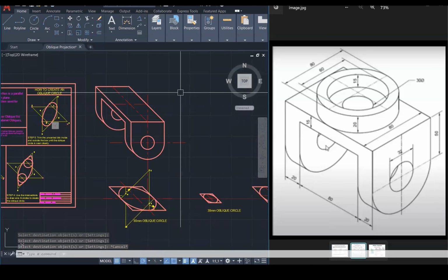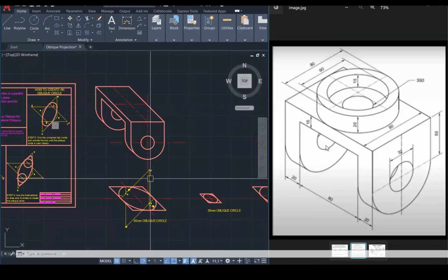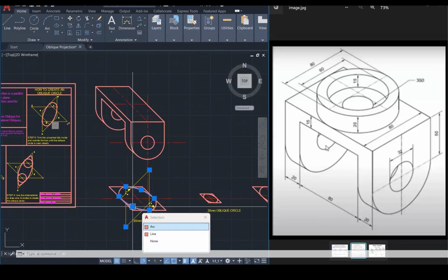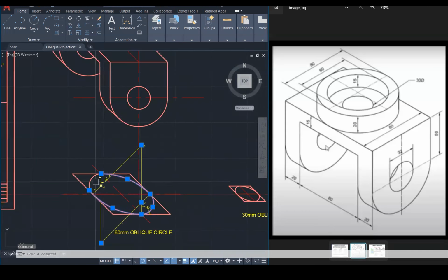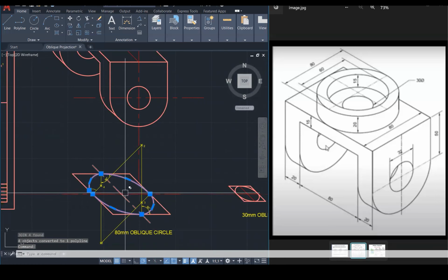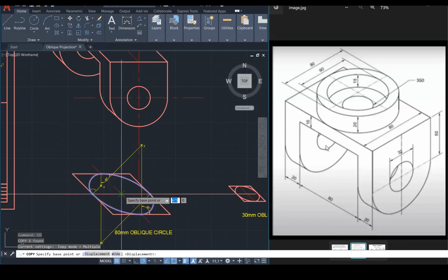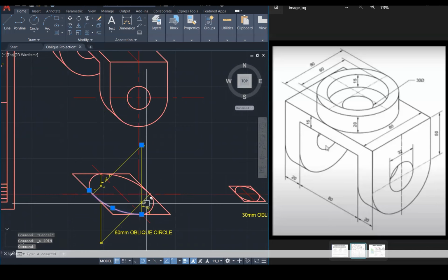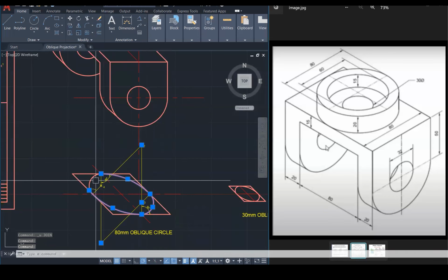Now, what I need to do is insert these circles. So I'm going to first grab just the circle. And I think the best thing I can do is to join these. So hit J for join, and there's one circle now. No longer parts. What I've just done, let me just go through it again, Control Z. The circle was comprised of 4 different parts.